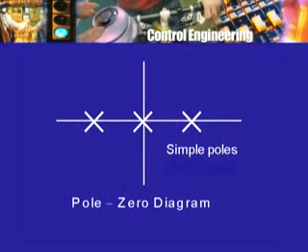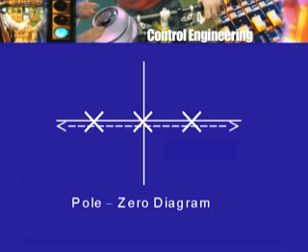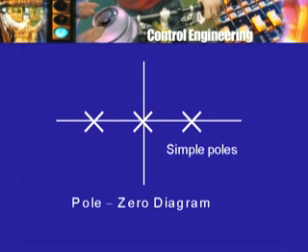So the three cases when the pole is real, and again on the pole-zero diagram, what will they look like? If the pole is in the right half plane, then pk is positive, s minus pk, pole is pk, so this is bad. If it is in the left half plane, that's okay. If it is at the origin, then we have to be careful. So if the pole or the root lies on the real axis of the complex plane, then these are the three possibilities that we have to consider. Remember, I am only looking at the case of non-repeated factors, or what are called simple poles.